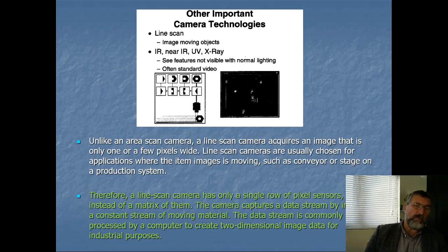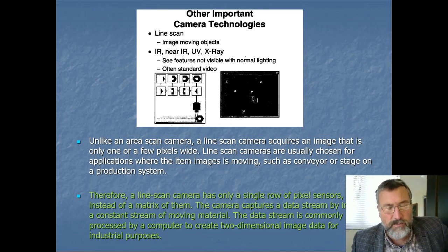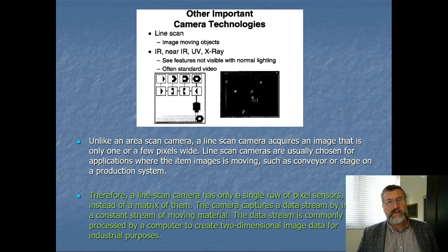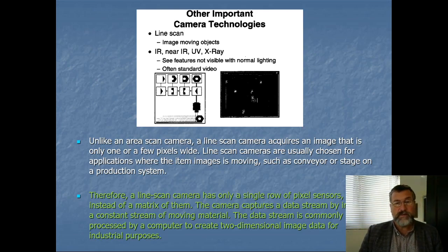The disadvantage of it is it's a bit complicated. It doesn't sound that bad, but you buy the cameras off one supplier, you buy the software from another supplier, you buy the frame grabbers from another supplier, and all of it's not necessarily that compatible. They don't necessarily want to talk to each other, because they all prefer their own software and so on. So sometimes just getting simple things working, like getting images synchronized at high speed with the lights going on and off, can be difficult. With the encoder can be surprisingly difficult. So it's a bit more complicated than just simply grabbing images on a conveyor with a normal camera.